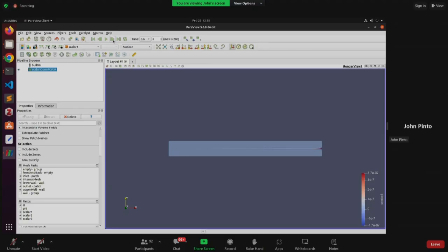You see that there is no scalar 3 forming, or there is very minimal. The values that you are seeing are e raised to the power -7. Whatever little amount you are seeing is because of the interpolation error in ParaView, and also maybe some problem in your schemes. If you use slightly higher order schemes, these are negligible values, like e raised to the power -7. Now this is for very low diffusion. That is, scalar 3 is not formed at all.